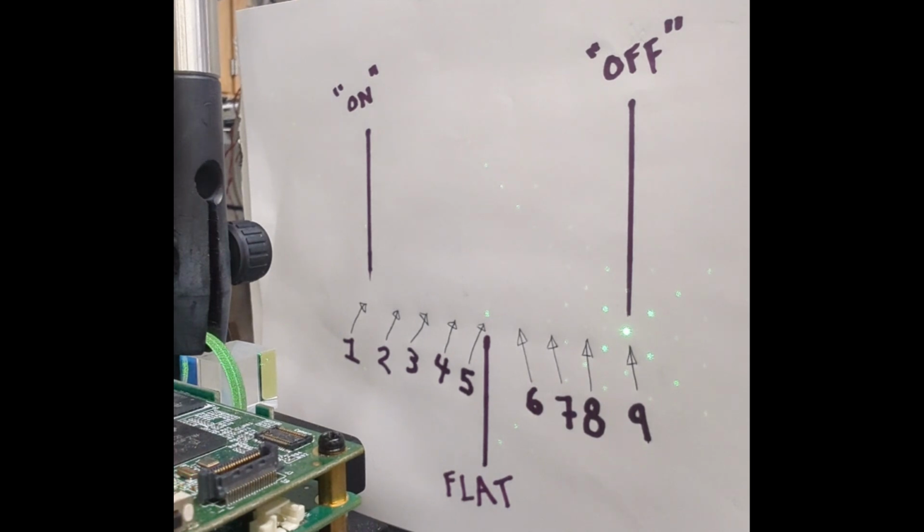Okay, so now the DMD has been turned on and the mirrors have been switched to the off state. If we ask the mirrors to switch to the on state, we'll see that the beam is steered to the on state. And we can go back and forth like this. This is traditionally how this device is used, in a binary on-off modality. Next, I'm going to show you 2 demos in which we can diffractively steer the laser beam between these on and off states by synchronizing the timing of the laser pulse and the transitions of the micromirrors.